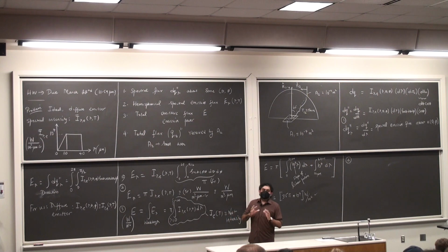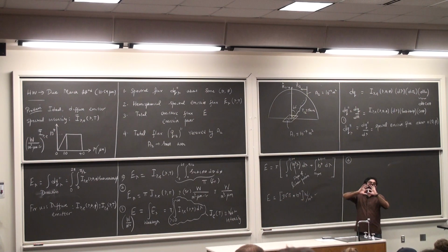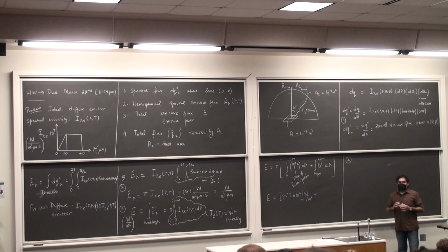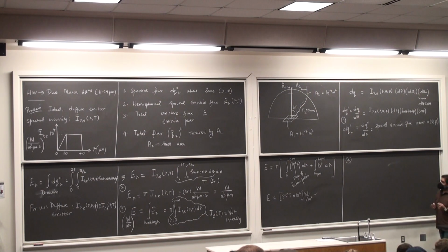Which means that all the radiant energy that is sent by A1 in the direction of A2 is all that is incident on A2. So in some sense, the amount of energy that is emitted by A1 in the direction of A2 is the irradiation for A2. Irradiation being the amount of incident radiation that you receive, right? The only sticky creature here is that it's not on the hemisphere, it's a surface sticking vertically up, and we will alleviate that in a minute.